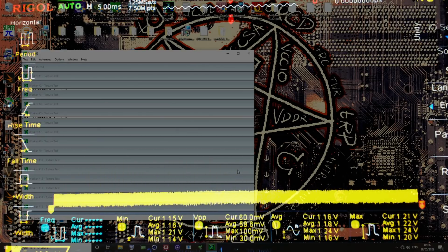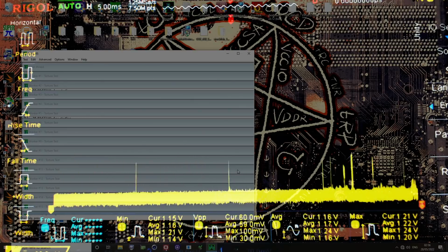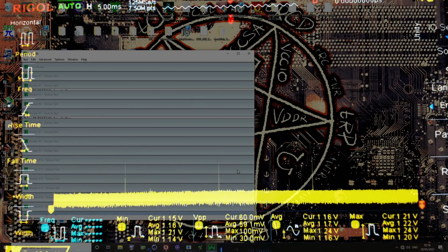But the whole time I was looking at this, the undershoot is still terrible. The V-droop isn't really changing very much, and I was sitting there the whole time wondering why we have all these LLC settings that basically don't do anything? And now it's like, no. If you switch over to Socket Sense, mode 1, I'm guessing mode 1 through 5 now have reasonable performance gaps, reasonable slope differences between them.